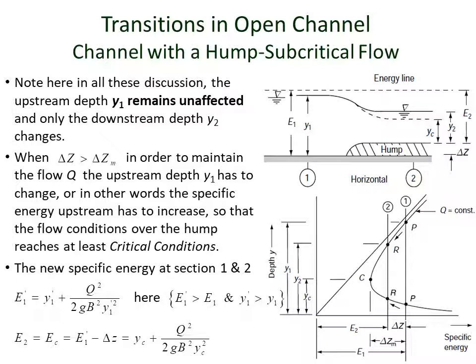Note that here E1 prime is greater than E1 and y1 prime is greater than y1. The downstream specific energy is of course the critical energy, as we discussed. So E2 is equal to EC, which is equal to YC plus Q square by 2g B square YC square.